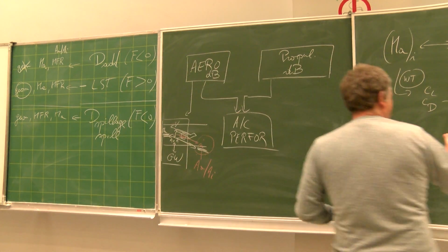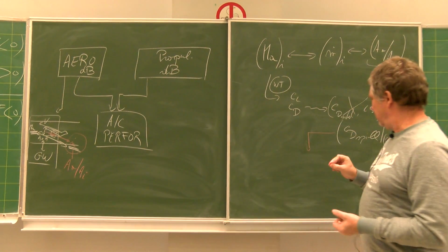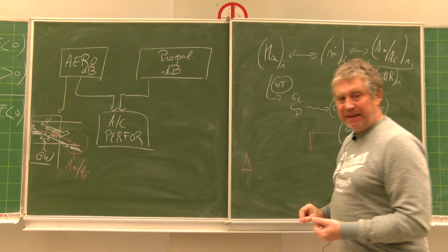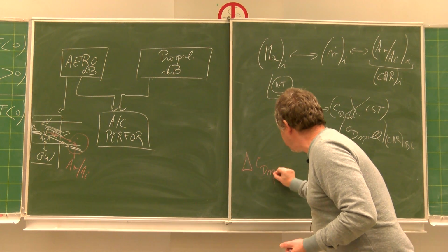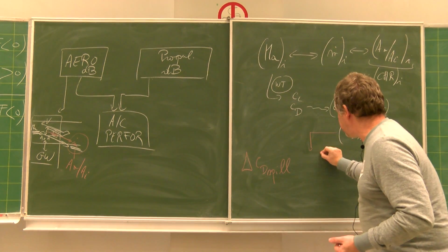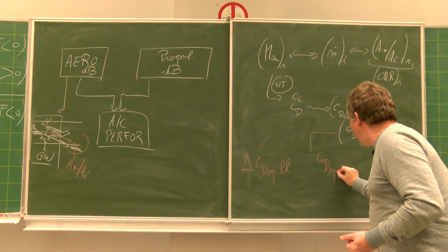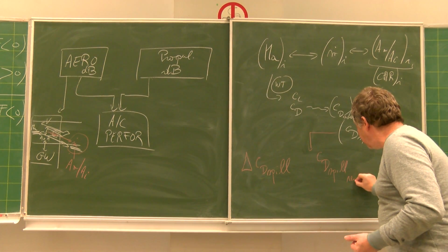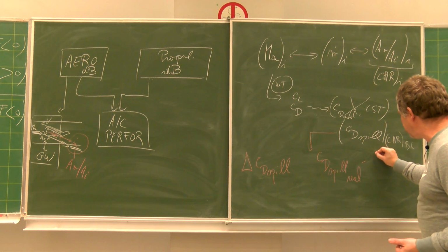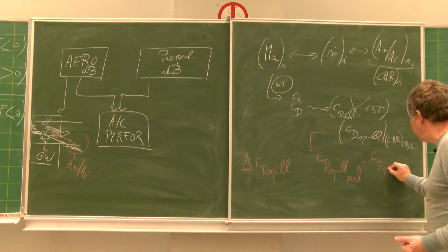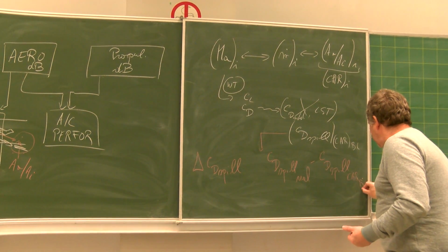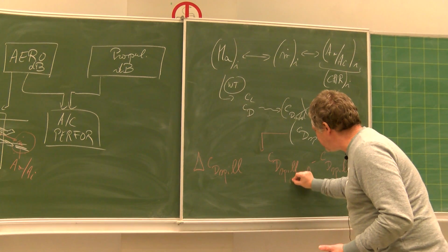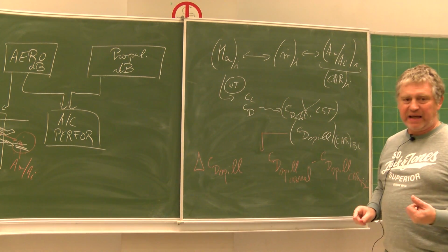They need to take into account the difference between the CD spillage, let's say real, minus the CD spillage for the capture area ratio baseline. When I say real, there is a real capture area ratio.